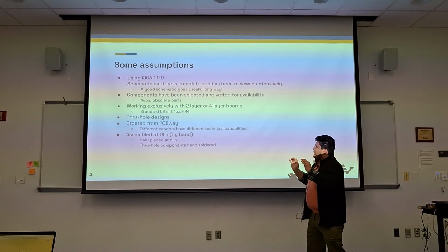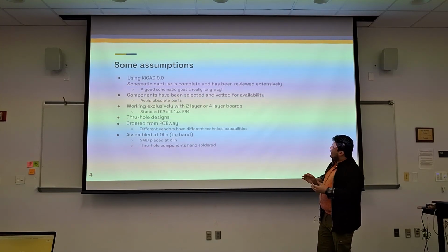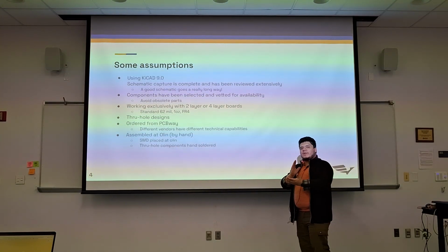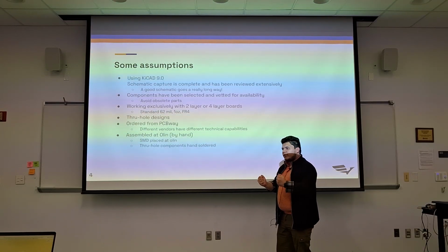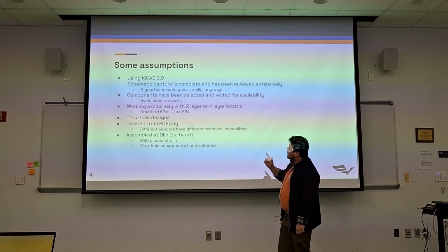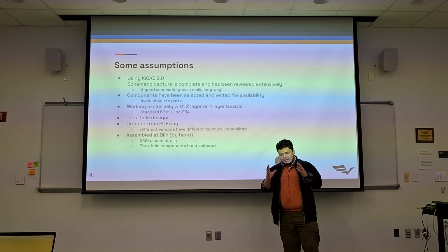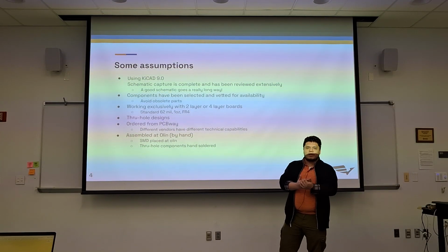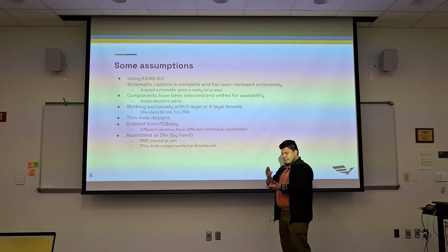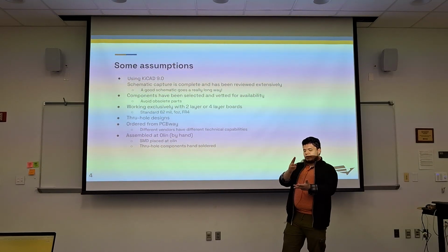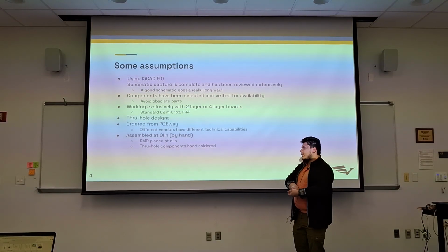One of the most important things before we even get to layout is I'm assuming that you've gone through extensive review of your schematics, or at the very least that y'all are confident and sure in your schematics, because having a good schematic really does go a long way. It helps you identify the requirements of the design, so if we're talking high power, differential pairs, etc., all that good stuff.